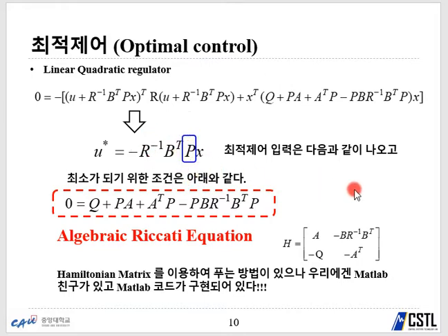On the other hand, if you select a high value of Q, the control performance is improved. However, with a high value of Q, the P obtained is large, so the control gain becomes large. So the control input is large. There is a trade-off between control performance and efficiency of input. Okay, let's start to see the Matlab code.